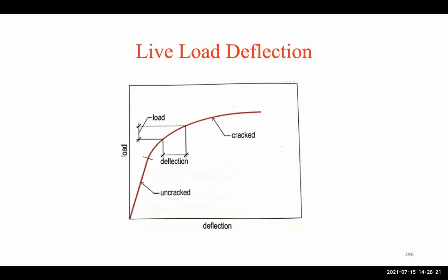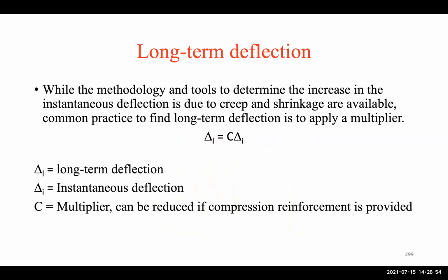So this shows the load deflection curve and how it changes from uncracked to cracked. And you can see the difference. You can see the difference between, if we consider it uncracked, that curve at the beginning will continue straight, theoretically. But since the concrete will crack after a certain point, it will follow that, and we can see the difference will be really, really high between both.